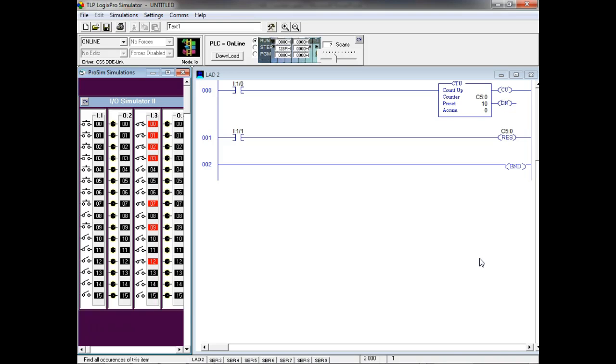But if I had a motor running 7,200 RPM and I had an encoder out there trying to figure out how fast it was going, these counters won't have a chance of keeping up with that. And they realize that. So what did they start doing? Well, on every PLC you buy now, they'll have a high-speed counter that is hardware supported. They have hardware counters inside the PLC that you can use for these motor speed encoders and stuff like that. An encoder gives us the speed of the motor and also gives us position.